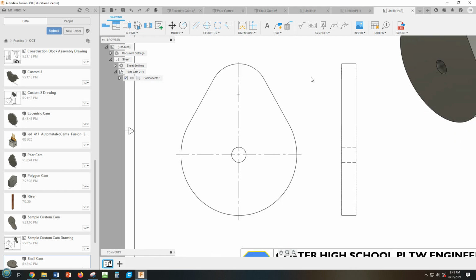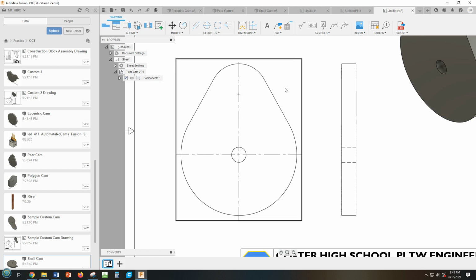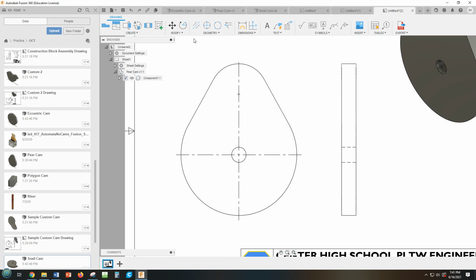that will work. Now, we're going to dimension the important stuff, which is where center points are, correct? Because this is a radius, it's okay for us to put a dimension on the radius instead of where we see it as a profile. So we're going to put that guy somewhere around over here, showing us that radius. We're also going to put this one up here, showing us what that radius is. And now we're going to put the distance between the center points from here to here.